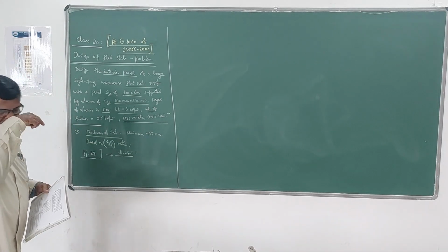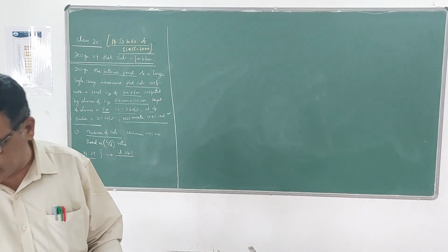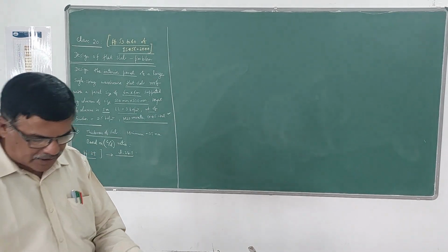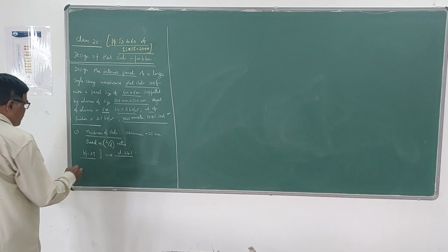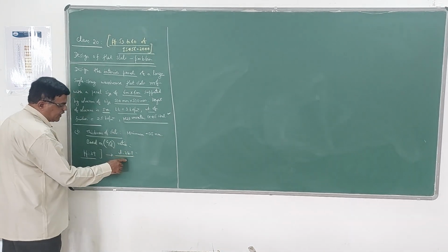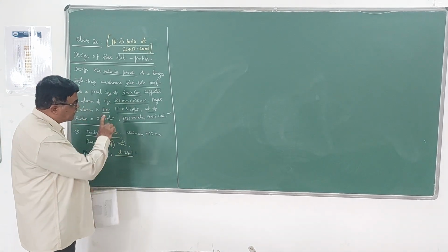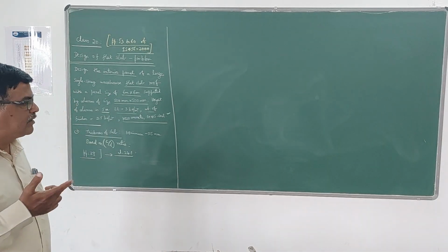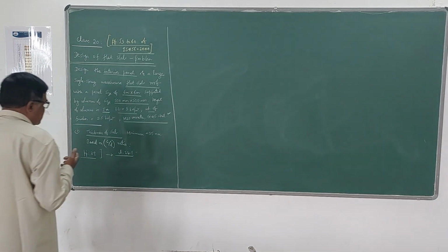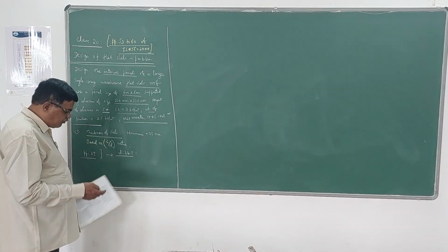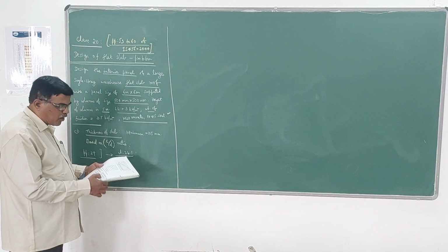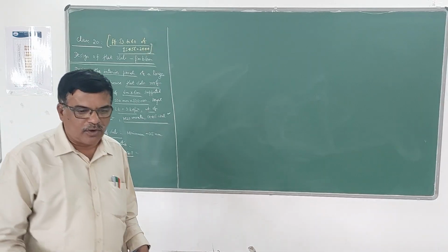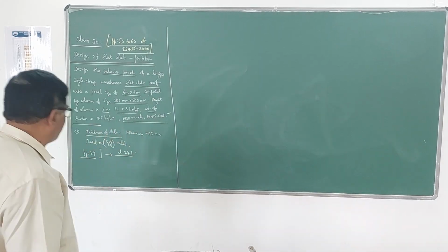That means here in this case, the value for continuous slabs is 40. It is given there. So you have to treat this flat slab as a continuous slab because it is supported by columns. We have to take it as continuous slab. So that value of 40 should be multiplied by 0.8 because we are using Fe415 steel.